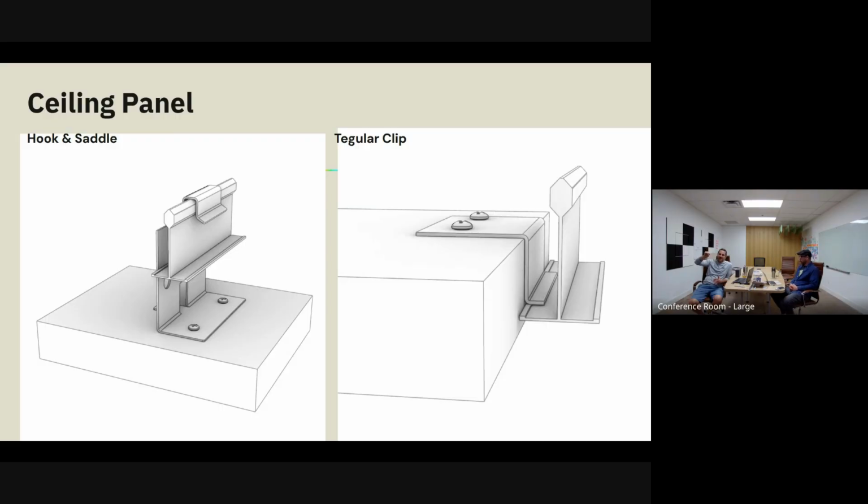But when you have a cross member, the back of the grid, this portion here, does not sit at the same height as your main. I don't have another piece, I wish I did. What you would have is your one that's coming in this direction sits just a little bit lower, or a little bit higher, depending on which grid you use. And it is crazy, there's 3 main grid manufacturers, and none of them are consistent.